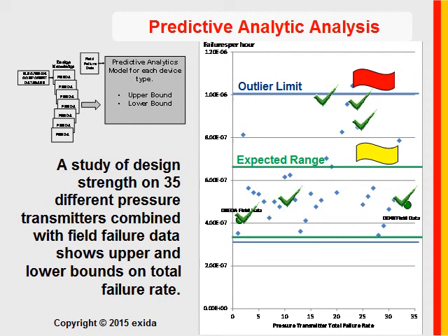Let me just think if I can think of any other good solution for you. If you are very confident that a valve has a design that's very similar to and has the same strength as another valve that is SIL certified, you might consider estimating your own failure rates by looking at the numbers of similar designs. I have done that as a technique, but of course then, since you're never sure, you would want to use a safety factor. I usually use at least a 2x safety factor when I do that kind of a thing.